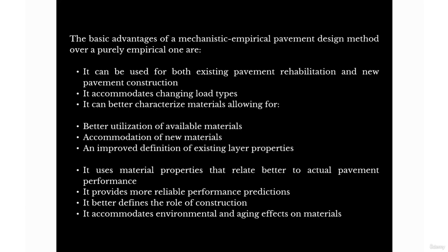Or if you plan on recycling the asphalt that you're going to remove from that section that you're rehabilitating, you can then incorporate recycled asphalt into your design. You can take that asphalt, send it to the lab, and they can give you all the parameters for that asphalt. Then you can incorporate it into your design, and it'll be a specific design to that aggregate that you plan on using.